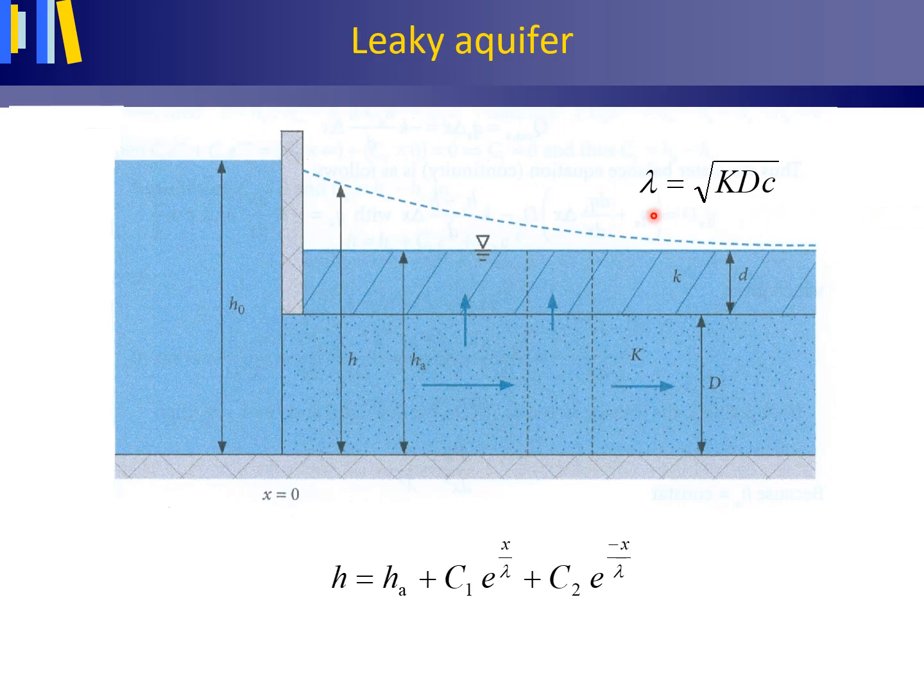The leakage factor is large when the aquifer has a high transmissivity and when the hydraulic resistance C of the confining layer is also large. Horizontal groundwater flow through the aquifer then dominates over the vertical seepage through the leaky confining layer, and as a consequence, in this Holland's profile, the hydraulic head in the aquifer, H, then diminishes relatively slowly with distance x from the left canal.